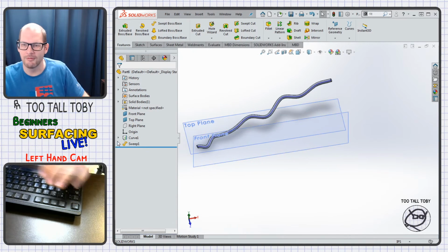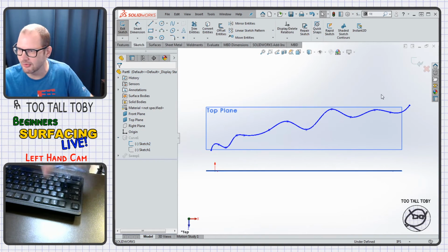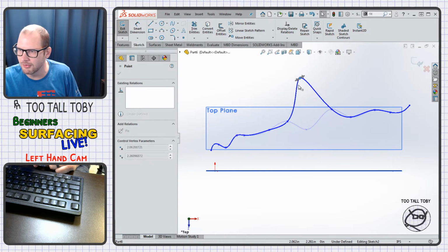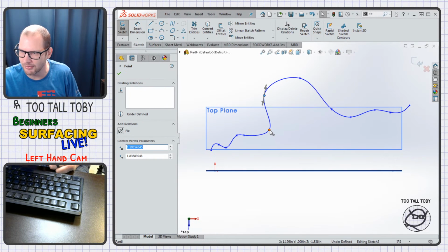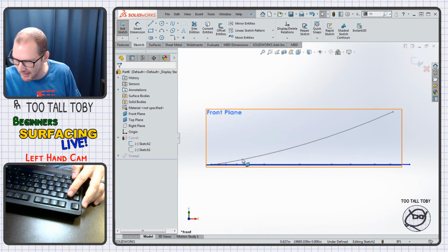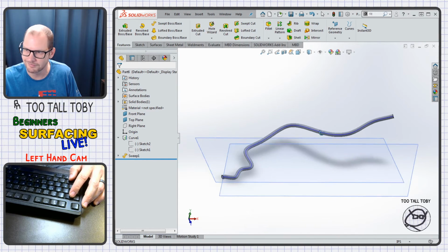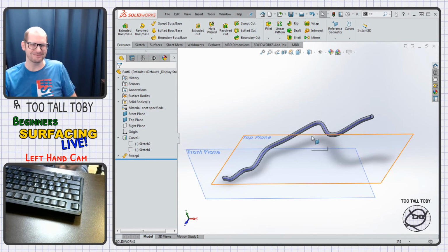So if you're looking at this from the top and you're routing a wire through your device, now all you need to do is move this over to here. I'm just going to route this wire through the device, and then from the front view, it needs to constantly be going up to navigate through this device. And now we get out of this thing, and there's our 3D sketch. That's so cool, or what?